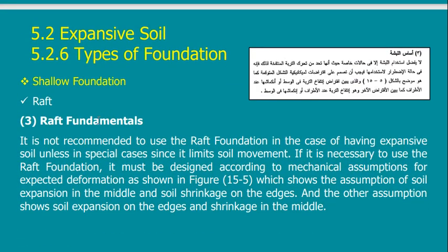Raft foundations, we said that raft foundation is the worst type of foundation for this. So this is an example of how to pay more and get less, because you are going to use a very complicated and expensive type of foundation to get the worst behavior, because it will be on top of the expansive soil.